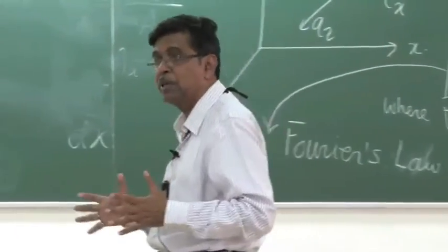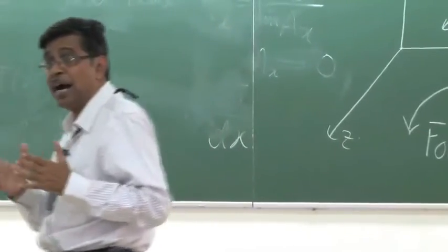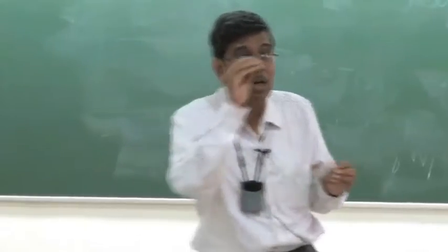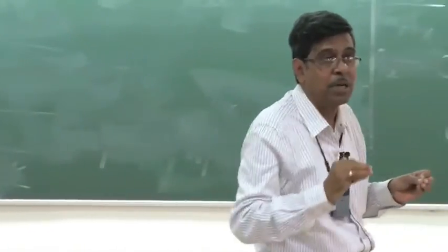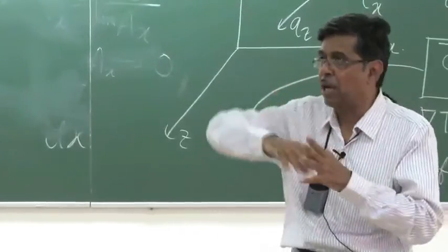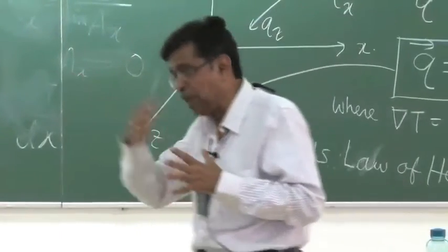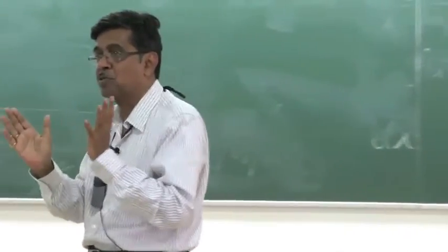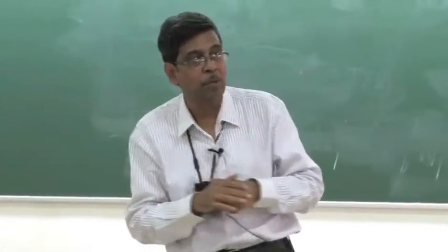You don't have to know much in depth of it, because this is not our course, this is for your information. And for those highly crystalline non-metallic solids, especially, examples being diamonds, graphite, silicon, quartz, this lattice vibrational wave propagates, and that propagation makes the major contribution, not the free electrons, to the conduction of heat.